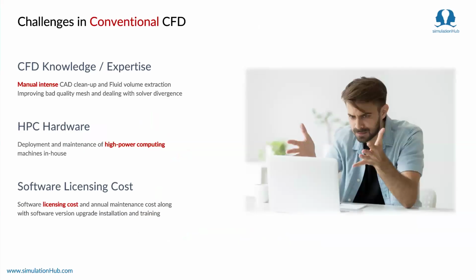Now, as we have seen, the advantages of CFD, how it can be used to predict noise in the design stage of the valve itself. There are challenges in the conventional CFD approach. First, it needs an expert. The process is also manual intensive, in the sense it needs a lot of CAD cleanup, fluid volume extraction, the mesh needs to be very good, and bad meshes need to be dealt with properly. There are also chances of solver divergence. So all of these things need to be taken care of.